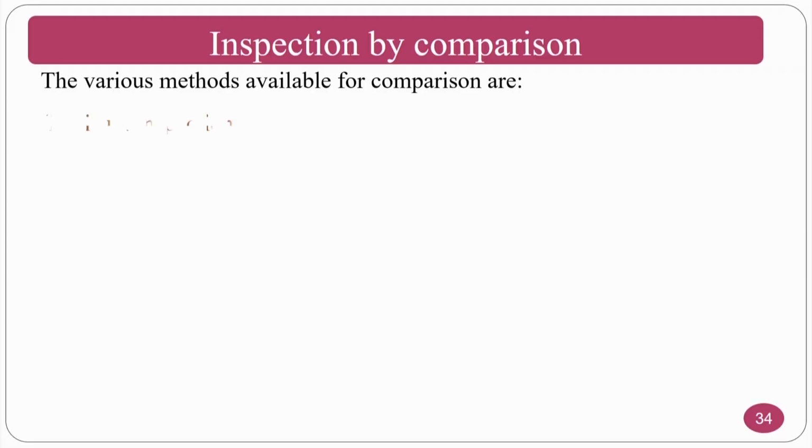If it is not matching, then you see the surface lay directions will be different. Your application may be somewhat lapping oriented, but the predominant surface roughness direction on the grinding sample will be a straight line type, whereas in lapping it is not; it will be random and mostly circular. So sometimes these small errors may mislead. So for inspection by comparison, various methods are available.